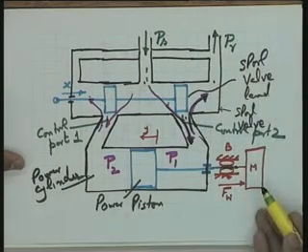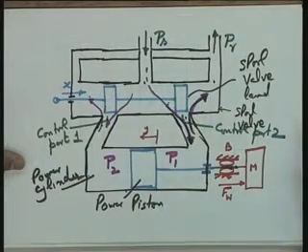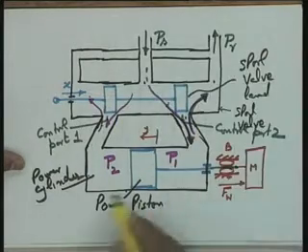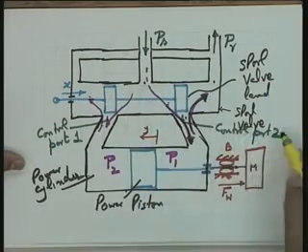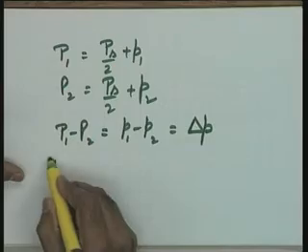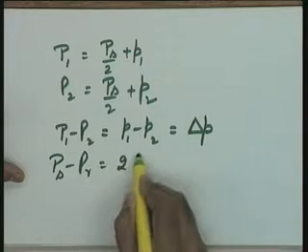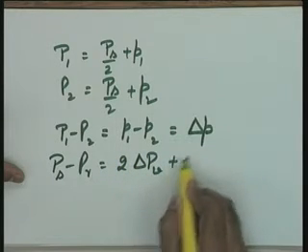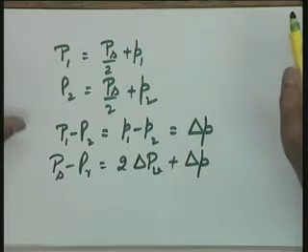The requirements do depend upon the load, and the requirements depend upon the port construction, because this supply pressure has to account for the pressure across the power piston and the pressure drops across the two ports, and therefore, I can write the pressure balance equation as Ps minus Pr is equal to 2 into del Pv plus del P.